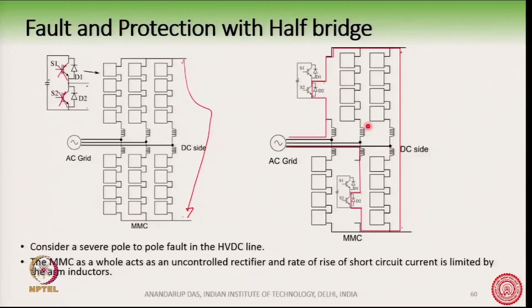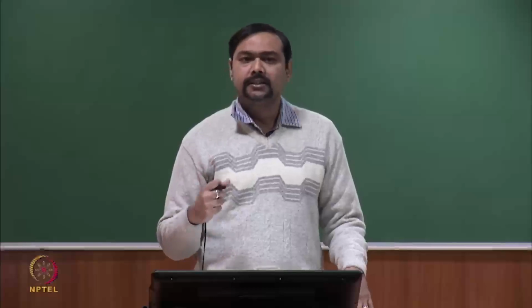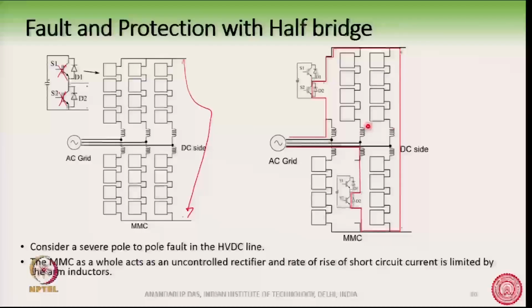Okay. So, therefore, using an air core inductor, we get less amount of inductance per unit volume, but we can avoid saturation of the inductor during this time. Okay. So, often these arm inductors are air core inductors to avoid saturation, but of course, the penalty is the size of the inductor is very big. With an air core inductor, the inductance obtained per unit volume is much less than when you use an amorphous core inside.